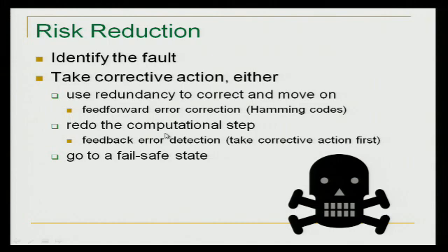You can redo, okay? On these embedded pacemakers, you know what they do? Every single time they read a piece of data from memory, they actually read it twice and compare. And if that comparison doesn't compare, there's an issue. So every single thing they read, they do it twice, and then they compare. For those safety critical systems like a pacemaker, that's necessary. Or again, you go to a fail-safe state because you can't fix it. Sometimes you can roll back, try again.